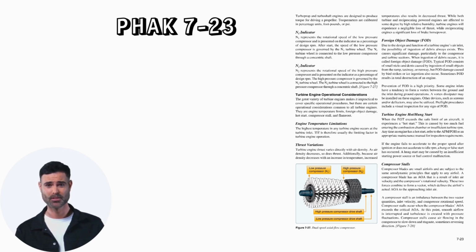Foreign object damage, FOD. Due to the design and function of a turbine engine's air inlet, the possibility of ingestion of debris always exists. This causes significant damage, particularly to the compressor and turbine sections. When ingestion of debris occurs, it is called foreign object damage, FOD.